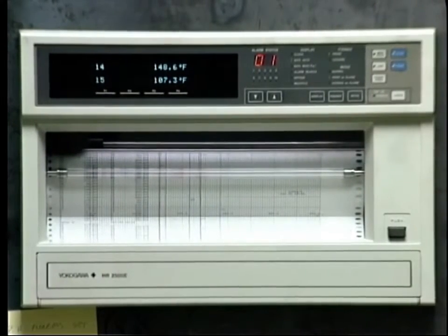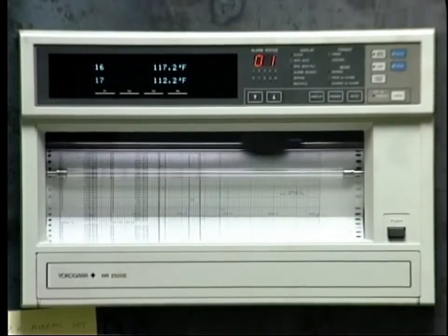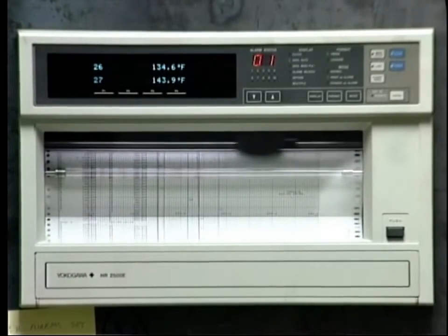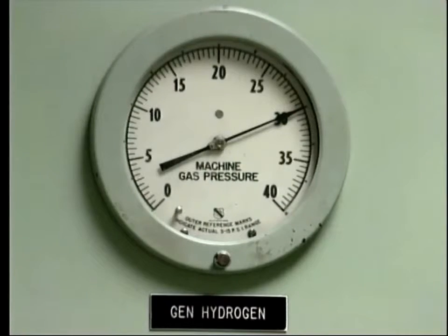If the internal temperature rises too high, it will damage the insulation and put the generator out of service. For this reason, distinct limits are placed on permissible temperature rise. In order to monitor this, temperature detectors are embedded in the stator windings at the anticipated hotspots. These readings are continuously recorded and alarmed when necessary. Forced cooling is employed to keep the temperature rise as low as possible, either by hydrogen cooling or air cooling. We'll be talking more about this in the next segment. But first, let's move our attention to the rotor.